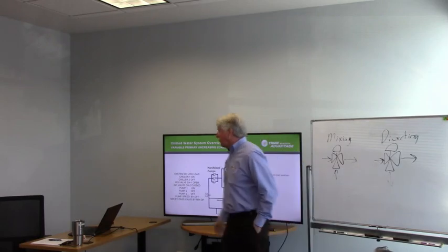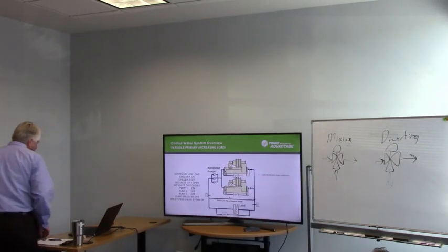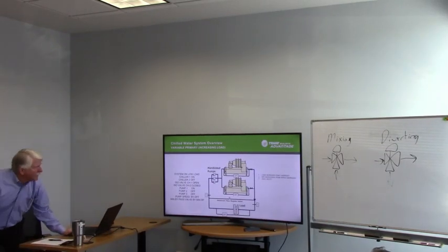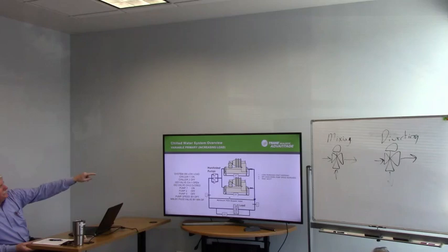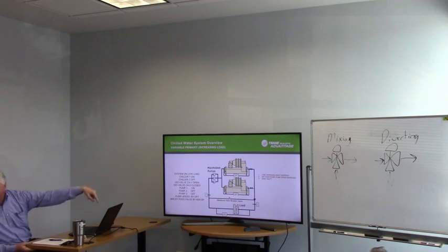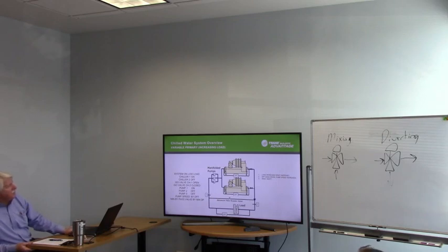So as the load increases, the DP, we're looking at it operating with one chiller right now. As the load increases, valves are going to open, the DP in the system's going to go down, and the pump speed will increase. Okay? So that's just with one chiller running.